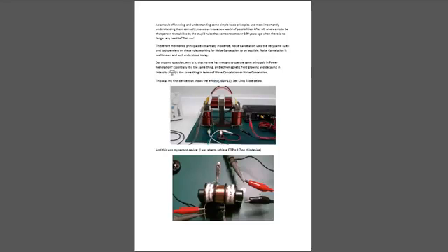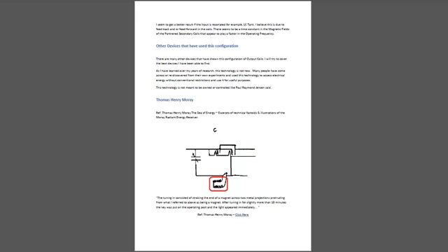This was my first device that shows the effects, 2010-11, see links table below. And this was my second device. I was able to achieve COP equals 1.7 on this device. I seem to get a better result if the input is resonated, for example, an LC tank. I believe this is due to feedback and/or feed forward in the coils. There seems to be a time constant in the magnetic fields of the partnered secondary coils that appear to play a factor in the operating frequency.